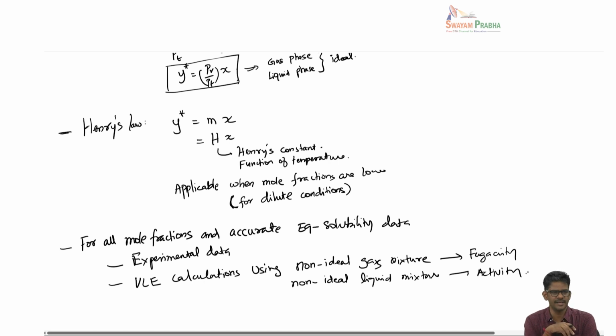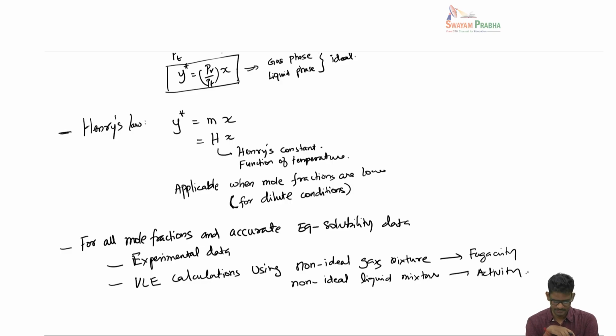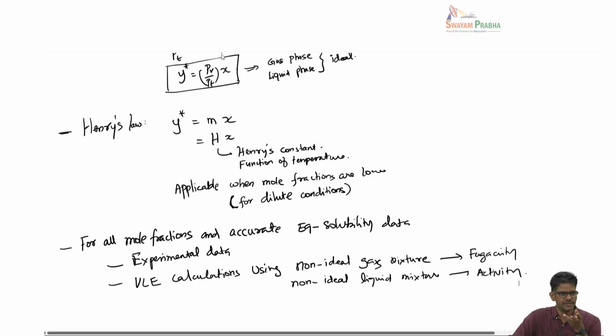Okay, so you can do a full scale VLE calculation over a range of mole fractions of your interest. So when I think about the equilibrium curve, you have to immediately relate that these data are obtained either from Raoult's law or Henry's law or a proper VLE calculation or experimental data. Okay, so we will not discuss further about how to obtain the equilibrium data. We will consider this as something now available for us for further calculations. So next we will move on to material balance.